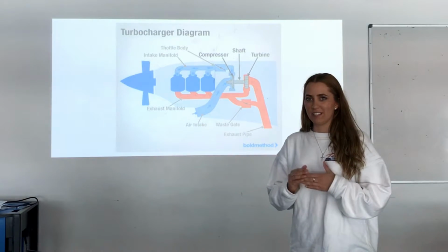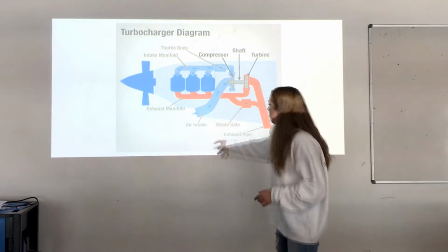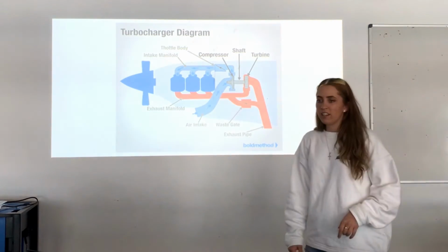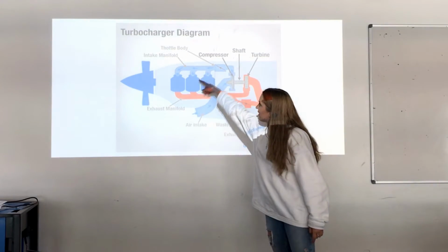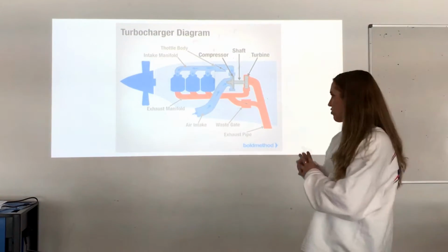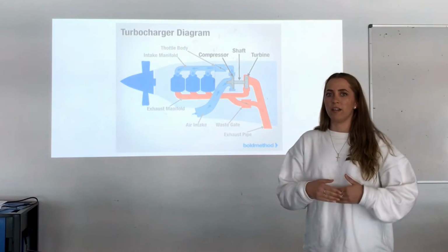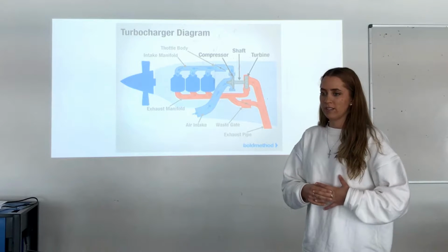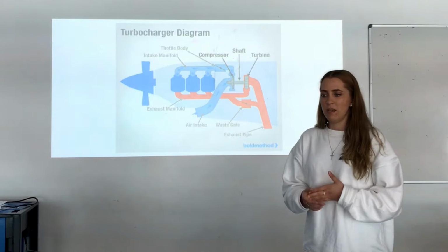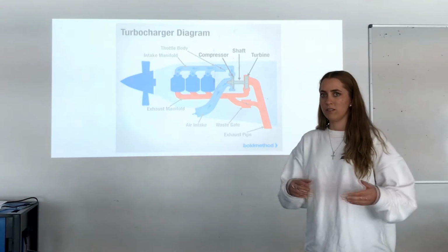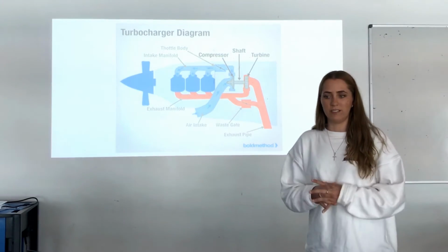To compensate for this lack of power, the air is pumped into the inlet manifold, or air intake. It then goes through the centrifugal compressor, which is here, and then it is sent out through there. The extra air that the compressor generates allows the engine to burn more fuel and create more energy. It doesn't increase the amount of power that can be generated, but it allows the power to be maintained throughout a climb, which is commonly referred to as normalized.